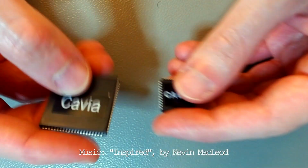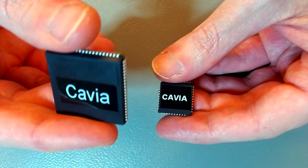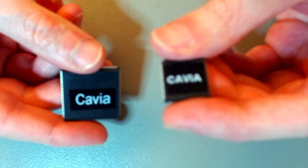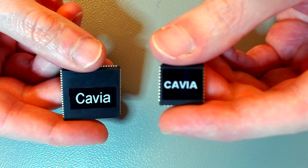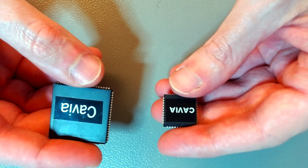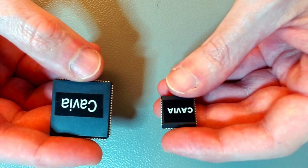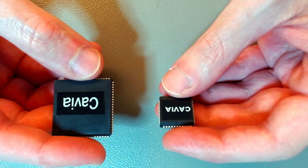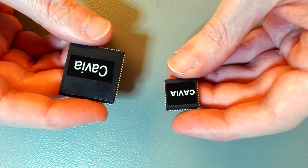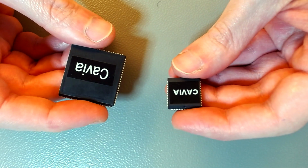Today we are going to put the video generation circuit together, but before we even start I want to break some news. CAVIA has become smaller. It has shrunk. I've managed to pack the logic in a smaller package, a PLCC 44 pins instead of the original PLCC 84. There were a few things I needed to do to achieve this shrinking, and that's what I'm going to explain to you now.